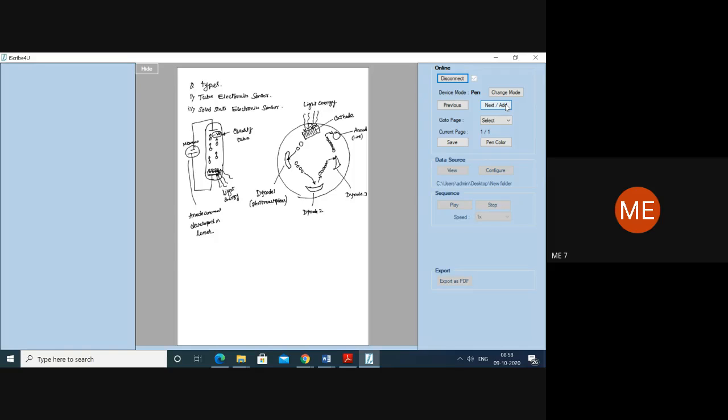charged value. Now what you need to understand here is, without the presence of the dynode, let's take an example, assume that there are only 2 liberated electrons. These 2 only will go to the anode, resulting in a lesser amount of anodic current. Now, as we have more dynodes, these dynodes will multiply the secondary electrons and accelerate them towards the anode, by which I am able to measure a good, appreciable amount of voltage.